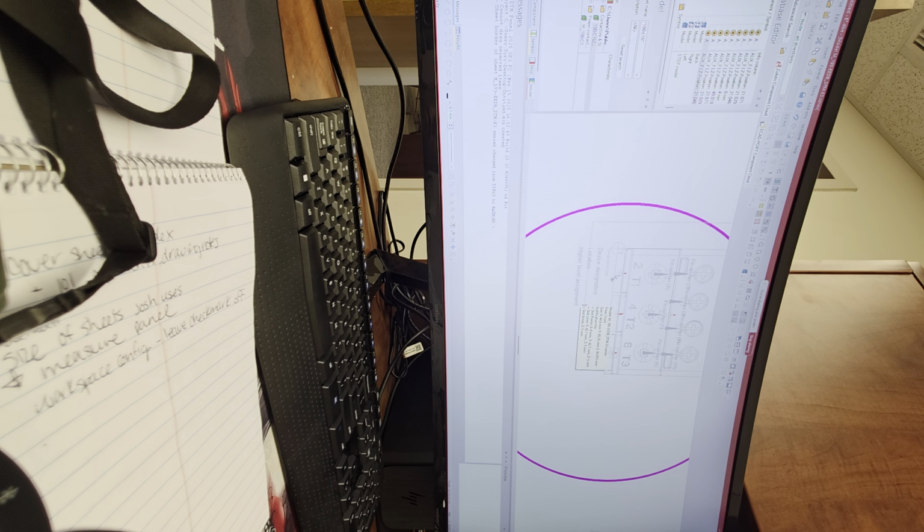Okay, so in this case, it looks like each contact has a slot point. This could be used for jumpers. It could be used for combs, as in mechanical combs, to combine multiple of these starters, like T1 to the next T1 to the next T1 together.